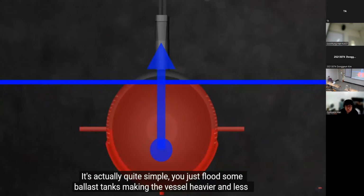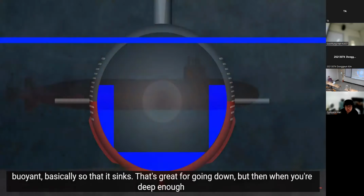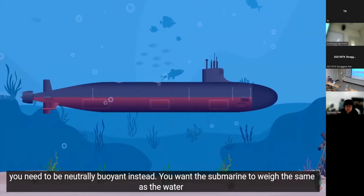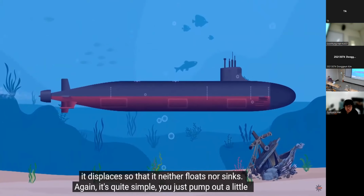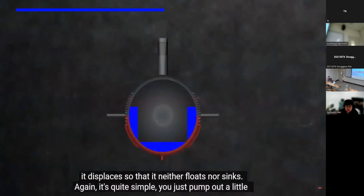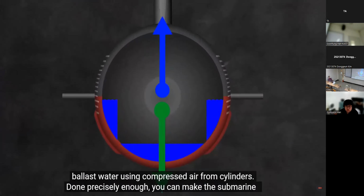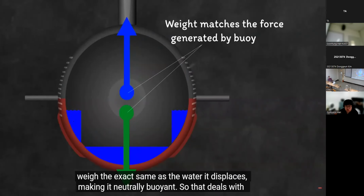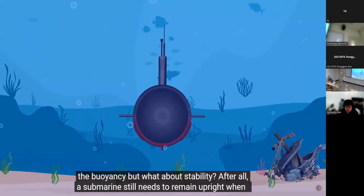It's actually quite simple. You just flood some ballast tanks, making the vessel heavier and less buoyant, basically so that it sinks. That's great for going down, but then when you're deep enough, you need to be neutrally buoyant instead. You want the submarine to weigh the same as the water it displaces, so that it neither floats nor sinks. Again, it's quite simple. You just pump out a little ballast water using compressed air from cylinders. Done precisely enough, you can make the submarine weigh the exact same as the water it displaces, making it neutrally buoyant. So that deals with the buoyancy, but what about stability?